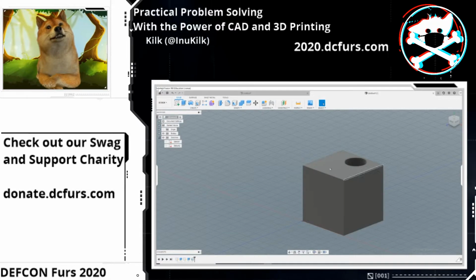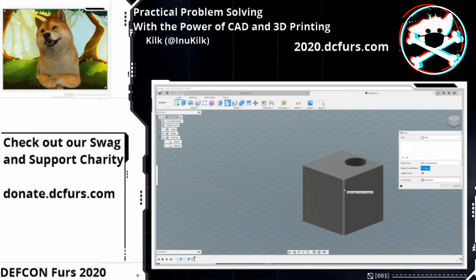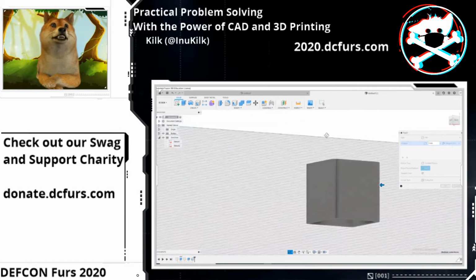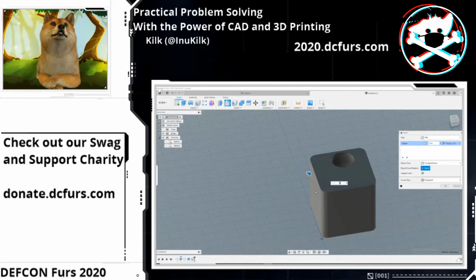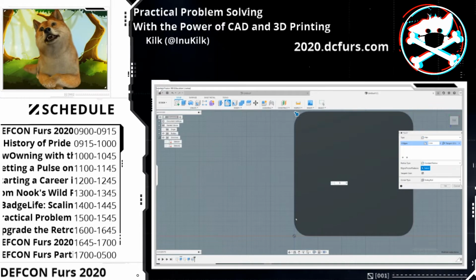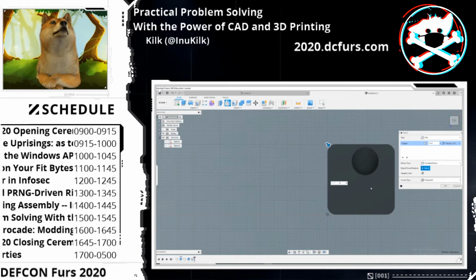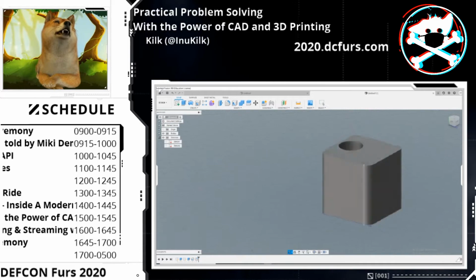Another thing to know is the fillet. You'll see a lot of memes about this if you ever do CAD stuff, because noobs or people like that love adding fillets to make it all look modernized and smooth and nice and fancy. So what we did here was we added a fillet that was 3 millimeters. The way that you want to think about this is, imagine there's a point here and it's rounding this by a radius. So we're rounding it by 3 millimeters. So we hit that. Boom. There we go. We have a curved one.